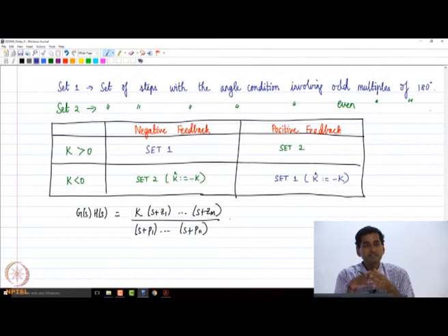Depending on your design choice, many times what will happen is that we will do a case study tomorrow, which will run through the entire process. Now that we are done with root locus design, I will take a physical problem, we will start from the beginning, derive a mathematical model, get the plant transfer function, then design controllers, find out what ranges of controller gains will stabilize the closed loop system, and then how to construct the root locus to satisfy certain performance requirements, right.